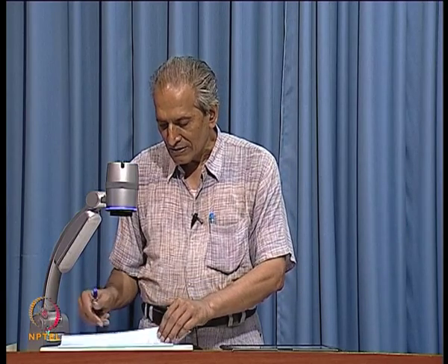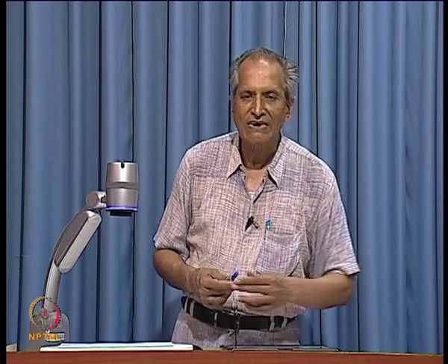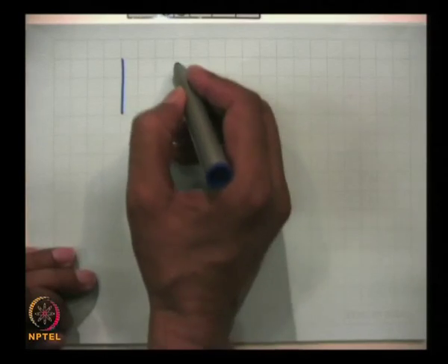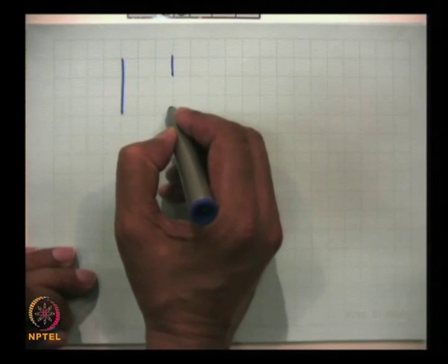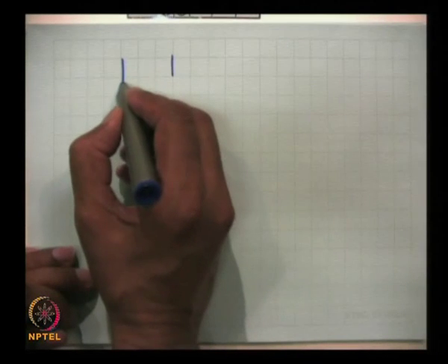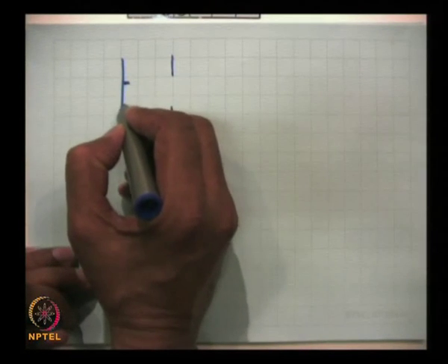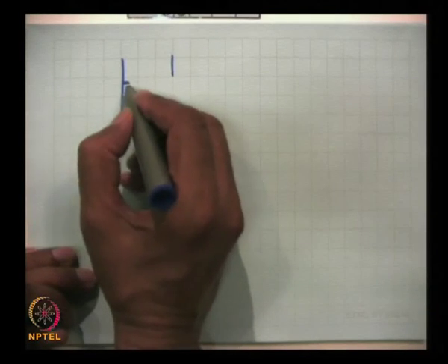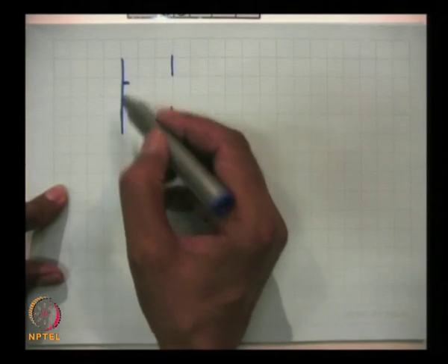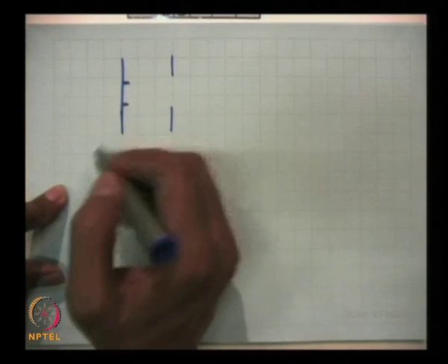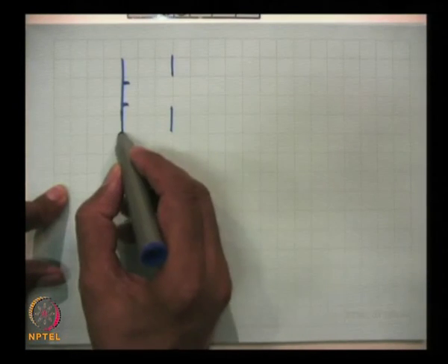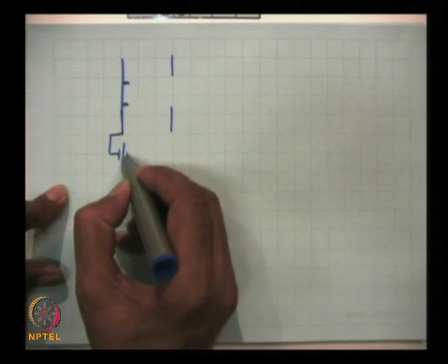A field emission diode is something like this. You do not have to heat the cathode. A field emission diode has a plate here and a hole here. On this cathode plate you have a knife edge, circular knife edge, very thin knife edge. I have drawn these two lines here, but this essentially is a ring. So, this is a circular ring of this much diameter, being a knife edge, and the distance between these two, this is a cathode and this is anode.